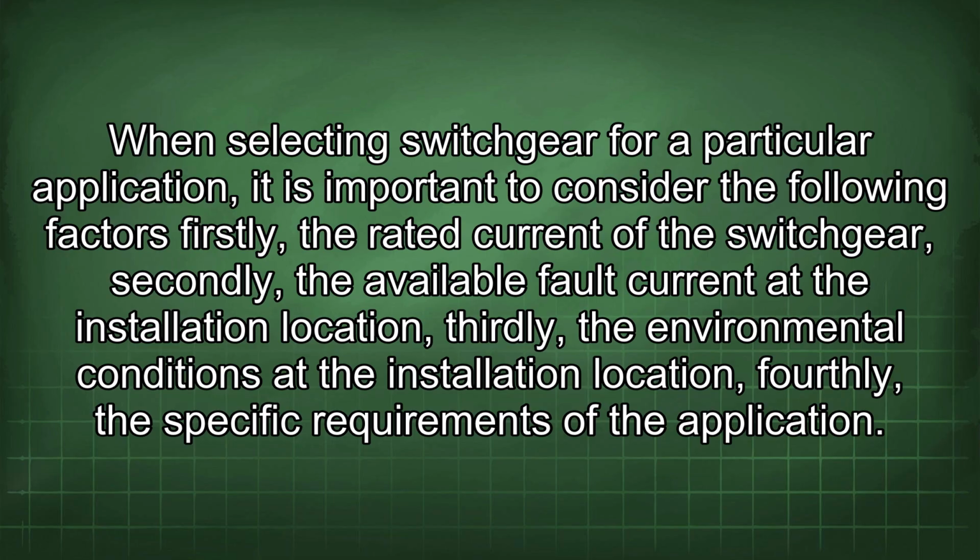When selecting switchgear for a particular application, it is important to consider the following factors. Firstly, the rated current of the switchgear. Secondly, the available fault current at the installation location. Thirdly, the environmental conditions at the installation location. Fourthly, the specific requirements of the application.